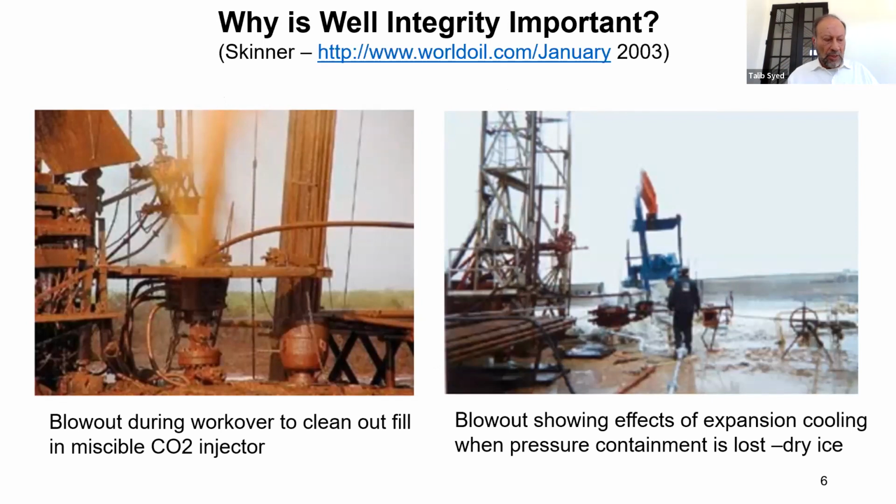Why is well integrity important? Here are a couple of instances of blowouts that occurred with CO2 EOR injectors. The one on the left is where a workover was going on in order to clean out the fill. And on the right, it shows the effects of cooling, which results during the expansion when pressure containment is lost.